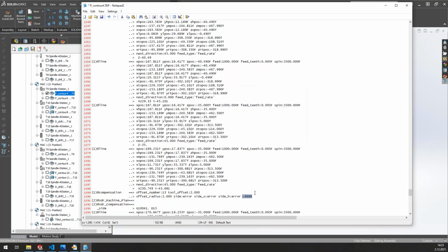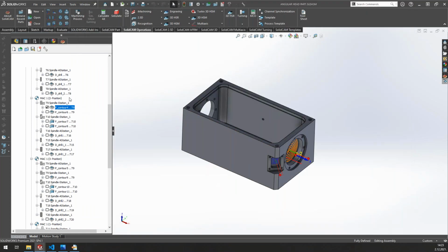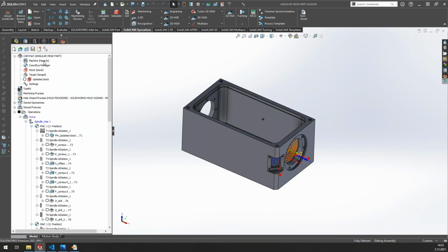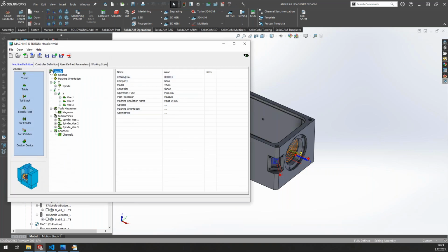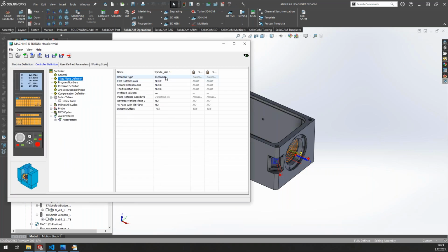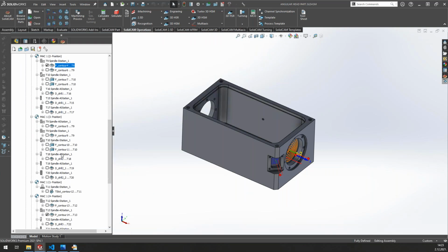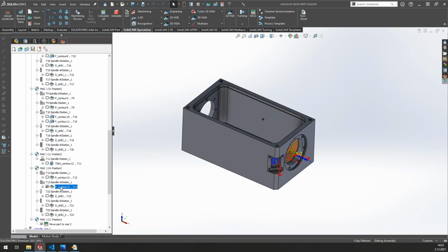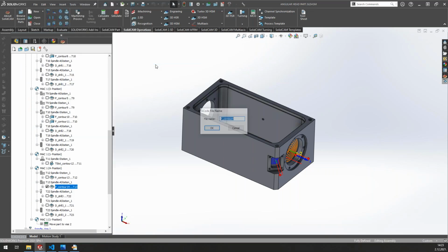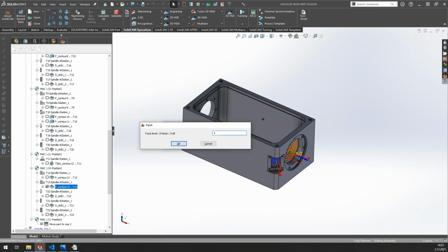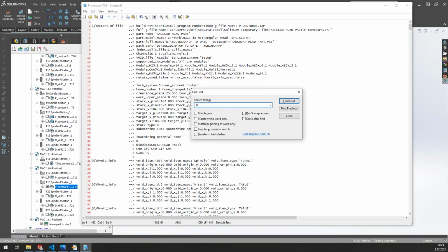So let me add the tilting of the plane to the post processor, even though the machine cannot support it. Let me add it just to show you the difference. So I will just transition from one to another, so it will automatically assign an order of rotation. I will save it. Now let's generate for both of these. I go G-code, generate. Let's use trace 5 again. Search for compensation.